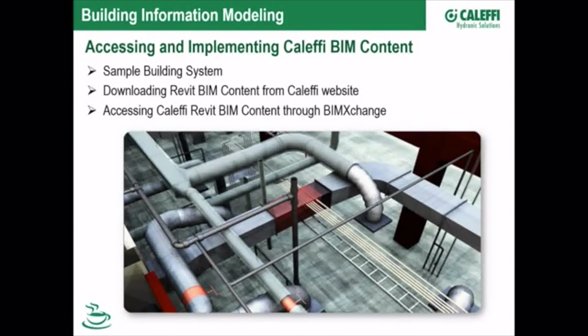The next part, I'm going to show you how to access the Revit BIM content from the Caleffi website. And then thirdly, our company creates a program that's a plugin for Revit called BIMXchange. And some of you may or may not be aware of this, but the Caleffi content is available through BIMXchange. And I'm going to show you how to access it and load it into your projects.